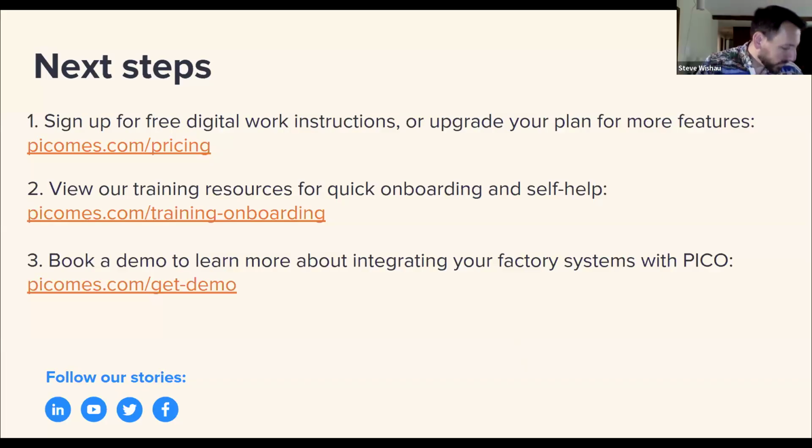Yeah, that's a good question. We actually encourage that. The Ignition server that I referenced is usually on a server rack or on a PC somewhere locally. All that needs to be configured is that local IP address and any security authentication to get there. If it's just a simple PLC, usually just an Ethernet connection and an IP address, and with open firewall communication between the Pico server deployment and that PLC or Ignition server, that transaction will happen.